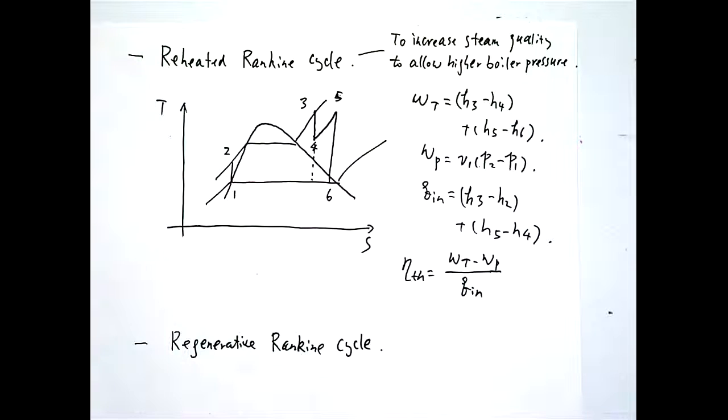And in that case, anyone recall what's the purpose of that regeneration? That's a heat exchanger where you're using the turbine exhaust to heat the compressed air before it gets into the combustor. So you utilize some of the waste heat in the turbine exhaust to preheat the compressed air, so that you can add less heat at the combustor to reach the same temperature. All right? So this is a similar idea, to reduce the amount of heat you add into the system.